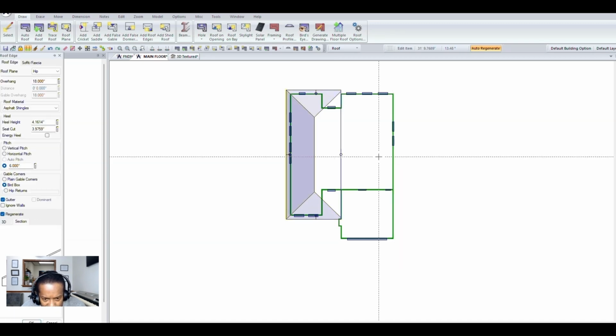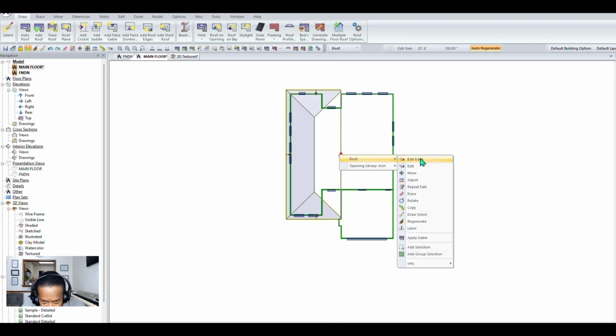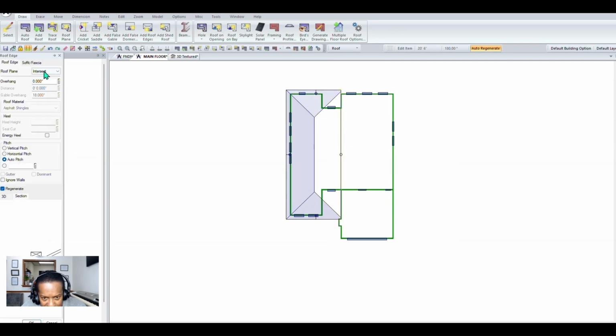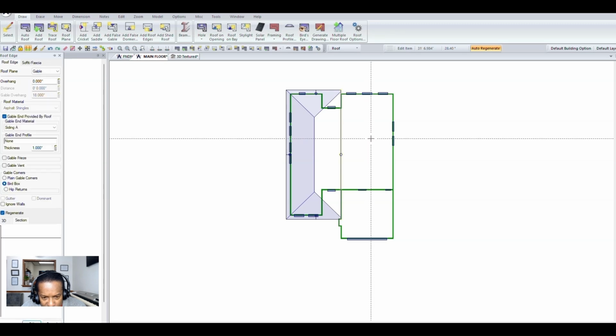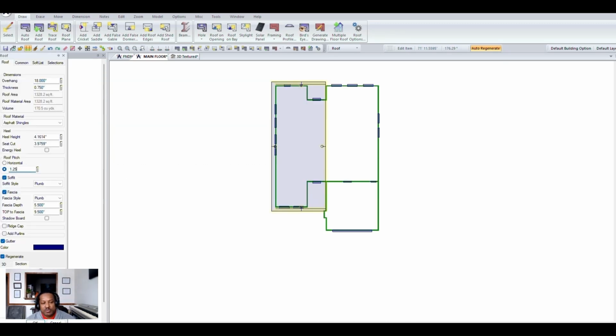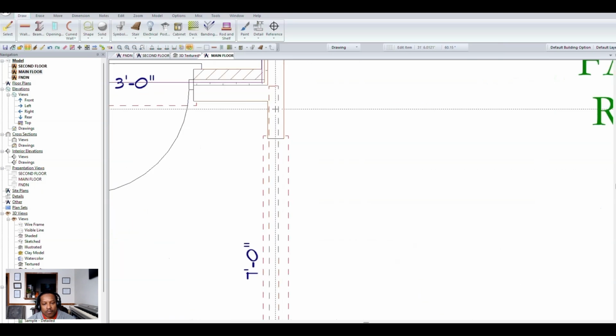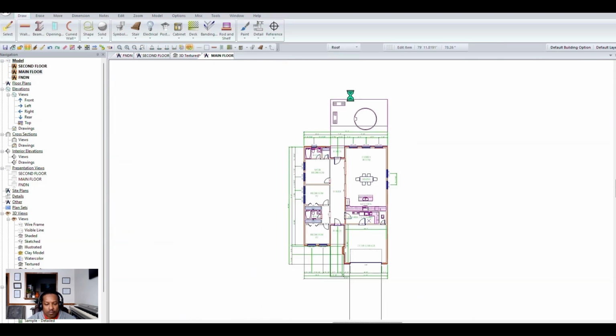In order to make the scallion roof, we'll do plain gable corners there. The inside of that needs to be a gable. And the front and back also on the tabs, if you see here, needs to also be a gable. All right, so we're going to make this pitch 1 1/4. So I'll set my beam height to the proper height so my roof can reference that. So we have a beam over the two openings.